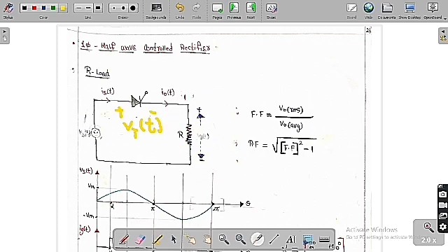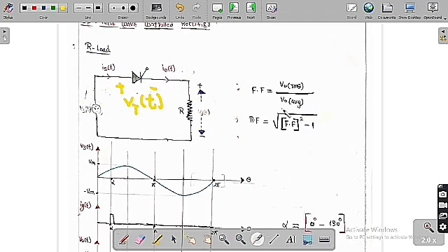Now we are going to find the different voltages, currents and expressions, everything we are going to study. These things I have already told you. Form factor, the easy way to remember is FRA, which is the ratio of RMS value by the average value, that is the output RMS value by the output average value. Means we are going to find the form factor of the output voltage. If you want the ripple factor, it is the square root of form factor squared minus 1. These are the formulas which I have already told you.